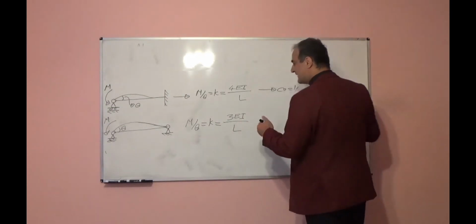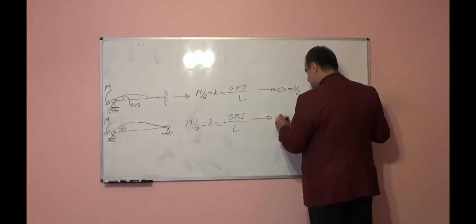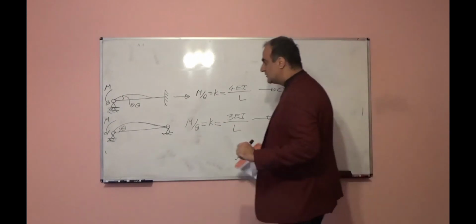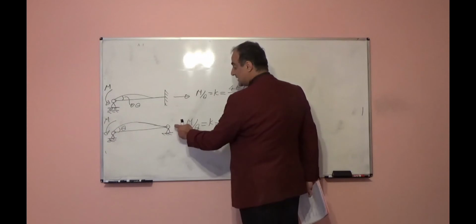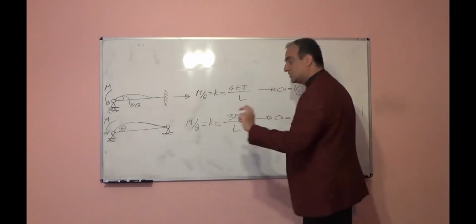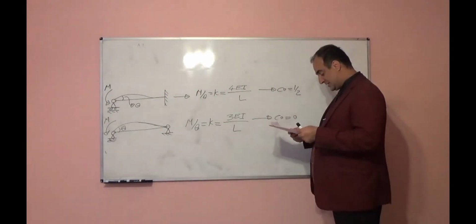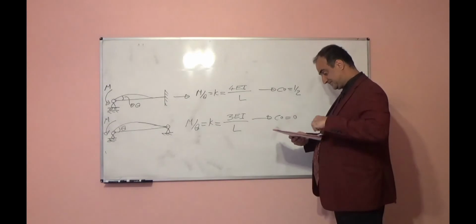The carryover factor here is equal to 0, because if I apply M here, the moment at the far side will be 0. It is hinged, there is no internal moment.